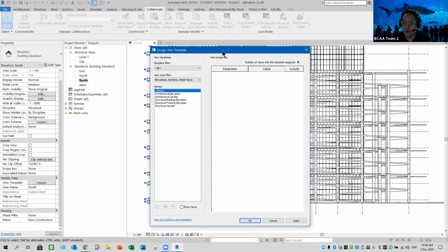If you learn AutoCAD before, is your layer reference layer, right? You set it to gray. Because AutoCAD you got to use layer lock, then they will show as halftone. Or if not, you use the gray color to override.